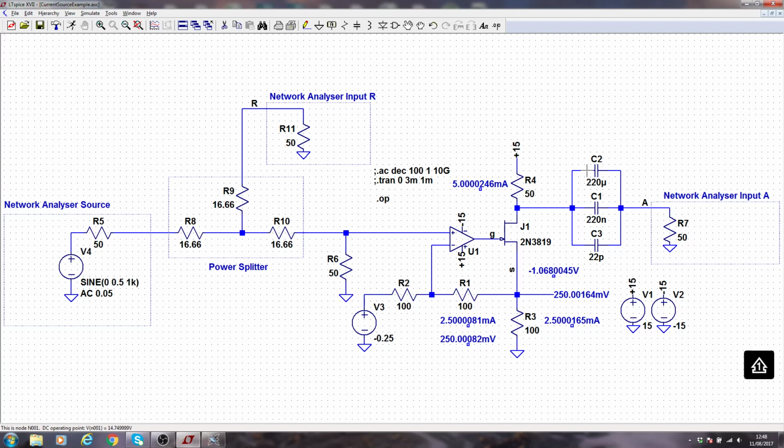It's like meshing your fingers together, where one set of fingers is the plates and one set of fingers is the dielectric. It's much more difficult to make a high value capacitor with a ceramic, because ceramic has not got as high a permittivity, and because the plate area is not as large. But altogether, C1, C2, C3 make a wideband efficient coupling for AC signals and blocking for DC signals.